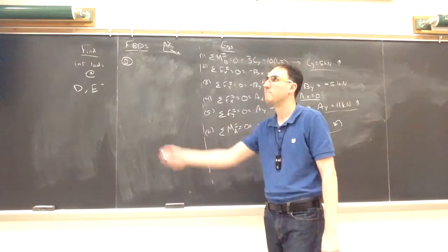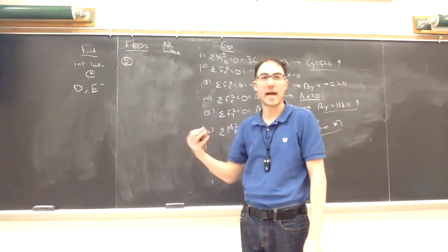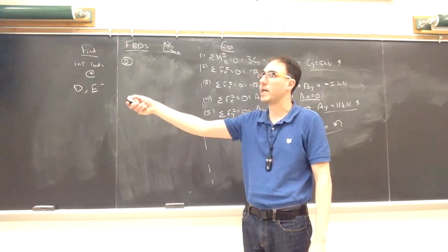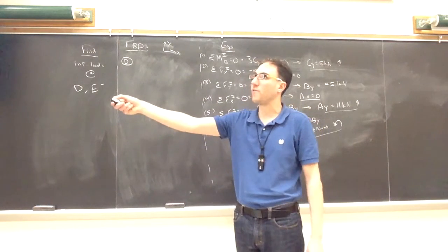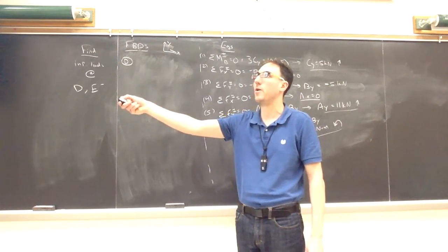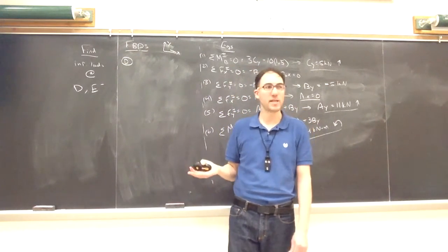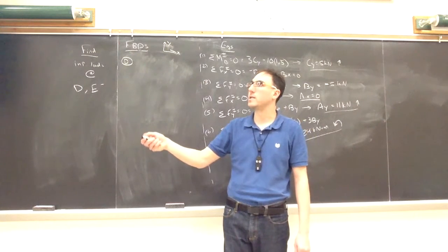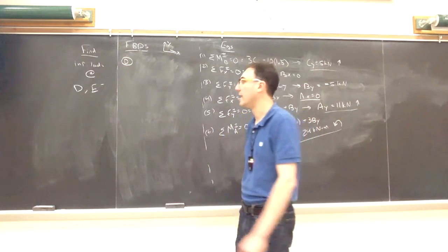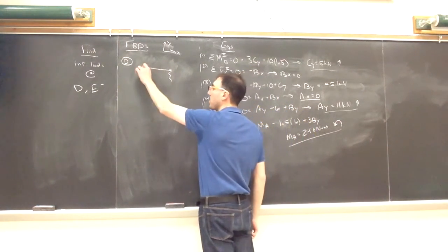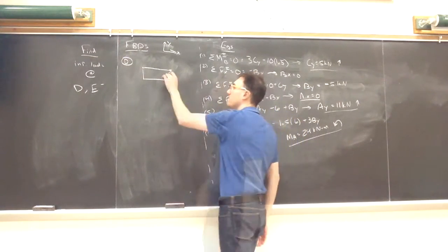And I have the option of taking everything to the left of my cut or keeping everything to the right of my cut. And actually here I have a couple more options. I could keep every part of the beam to the right. I could take just from D to B as well because I know what's happening at B from that previous step. So I have probably 3 different options here of what to do. But because to the left of D, just less is happening, I'm going to take everything to the left of D as my picture. I think that's going to be the simplest way to do this. But any of the methods would give us the same answer.